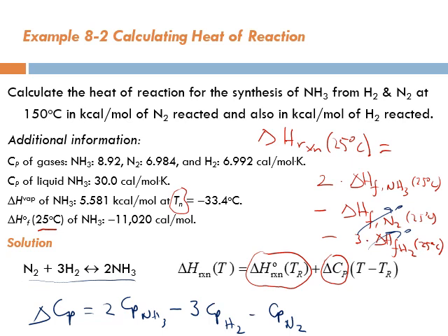Tamam. So the reaction is going from 25 degrees C, correct, to 150 degrees C. So the reaction was first calculated at 25 degrees C, right? And then we are using that to calculate the delta H reaction at 150 degrees C. So when I'm going through the calculation, not practically, not actually, from 25 degrees C to 150 degrees C, do I have phase change?